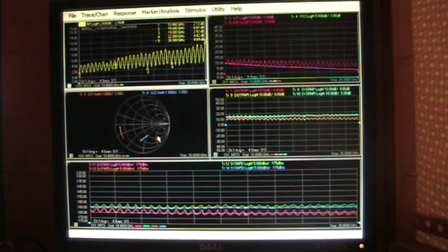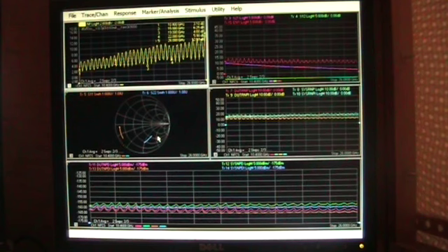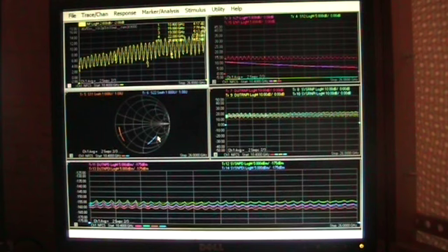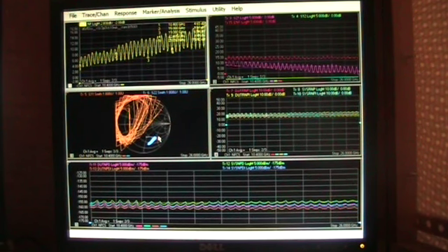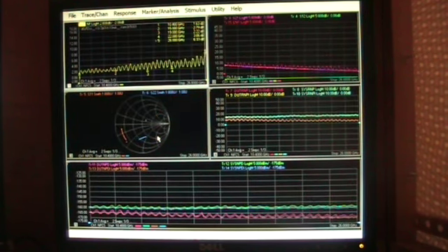In order to measure all of the noise figure points across the gamma space, in this particular configuration it would take approximately 1 hour to complete. That's with 4 or 5 bias points. In order to speed up the system, we reduce the number of measurement points to just go in 1 gigahertz steps. Usually when that's the case, we can measure from 2 to 50 gigahertz in 1 gigahertz steps for 10 bias conditions in 1 hour.